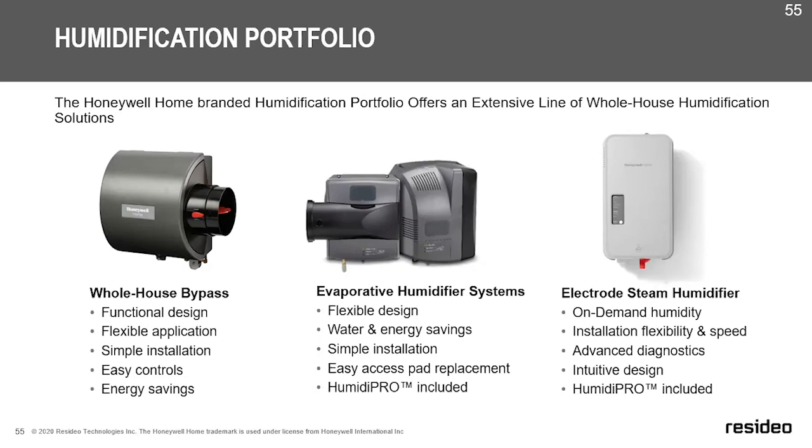On the right, you have your steam humidification. So again, you can do on-demand humidification. I could set it to a certain humidity set point, and I'll get there if I'm sized appropriately, because I don't rely on any heat outside of the actual internals of this unit.